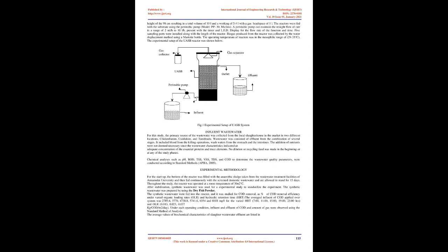Most of this wastewater is treated physico-chemically, requiring large quantities of chemicals and energy to dry the effluent and generating 20 grams of sludge per liter of water. The deposition of the sludge is difficult, thus limiting the use of this technique. A better option to reduce the generated biosolids might be anaerobic digestion using upflow anaerobic sludge blanket reactors, UASB, Spies, 1983, Young and Dahab, 1983, Young, 1991.